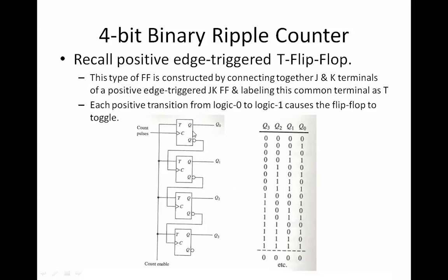As you can see, it takes time for the value to pass from one point to another. Let us say I have given a count enable value of 1. So 1 is coming here, but 0 is here, and 0 means it is getting disabled, so this 1 will not come here. It is waiting for the enabling.